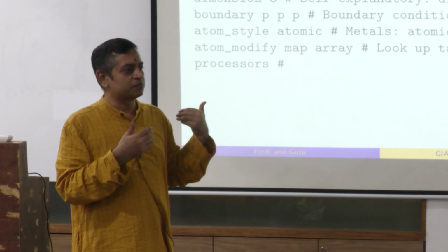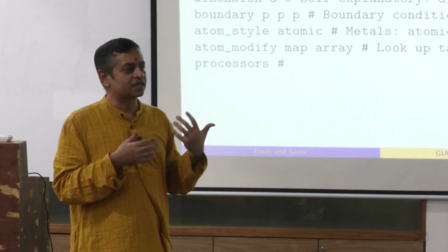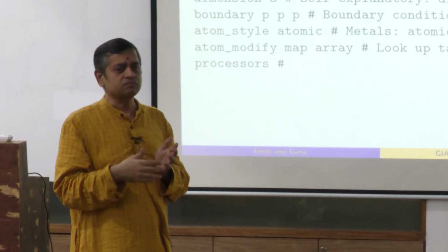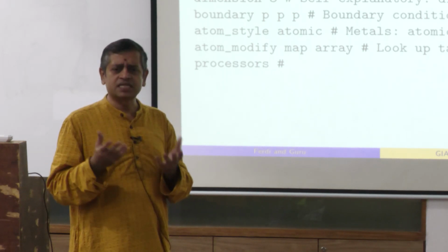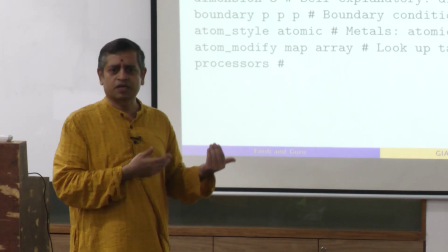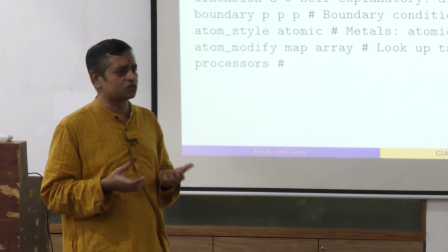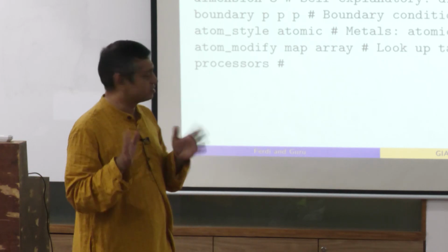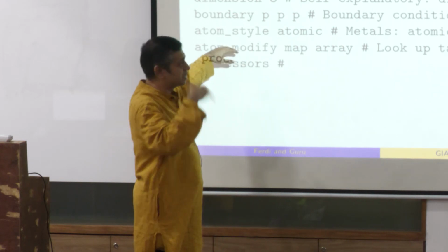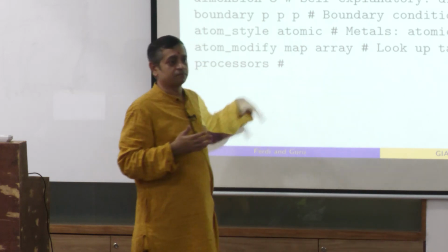We implemented a very simple minded MD yesterday, which did not talk about the neighbor list and linked list and things like that, which, if you go to a textbook like Allen and Tildesley, you will see. Allen and Tildesley is for liquids. If you do MD simulations for liquids, things are all moving around, so these things become much more important, and starting from how you label the different atoms and molecules and so on, there are algorithms which we did not talk about. But if you are using LAMMPS, because it has all these capabilities, you have to know some of these things.